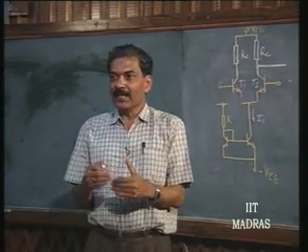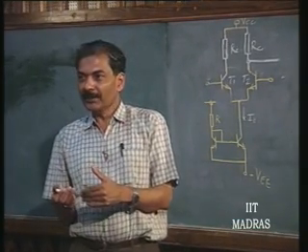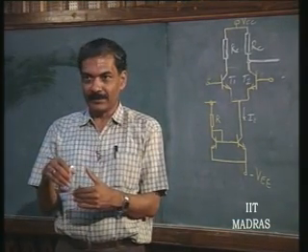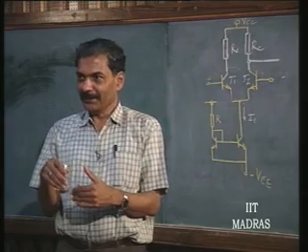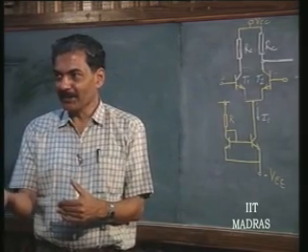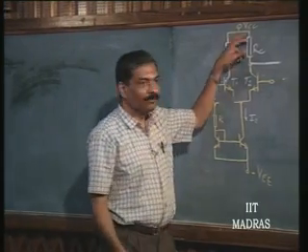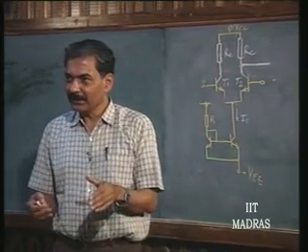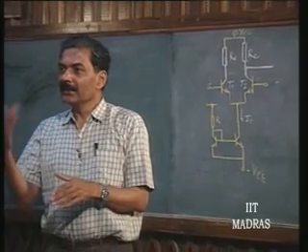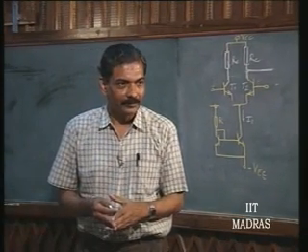As far as the gain itself is concerned, it is not infinity. The current source impedance will be coming as the load impedance apart from the input impedance of the next stage. So, actually speaking, in a practical situation, the current source impedance will be replacing RC as well as the input impedance of the next stage. These two will come in parallel.